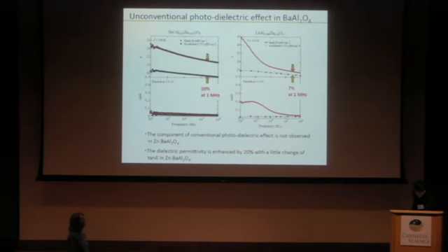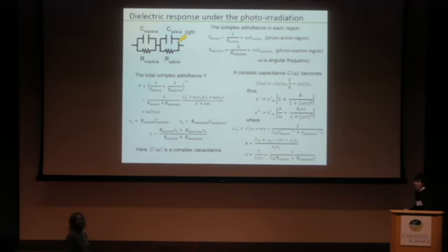Practically, you can distinguish it when you measure permittivity on samples with different thickness. If you have different permittivity in samples with different thickness, then it means that you change just conductivity and the depletion layer by electrodes will be all the time the same. You will have all the time the same capacity with different thickness. It means different permittivity.